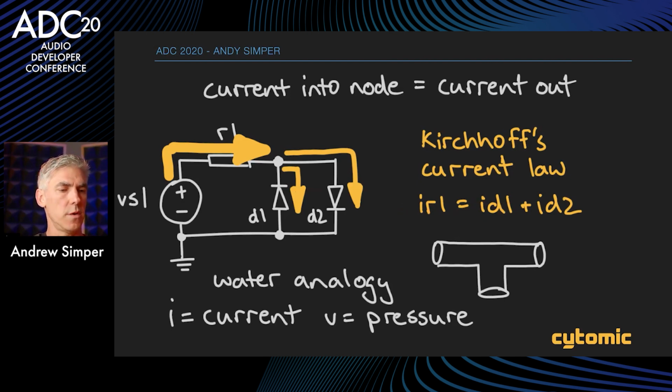The important thing to note here is that when you're dealing with circuits, you've got two numbers: the current and the voltage. This is the real world analogy. You still have a current, which is the flow of water, but the voltage is the pressure of the water. These are physical things that are natural with water. When you're into DSP, you're stuck with the V. You've got the signal and you're processing that, but you kind of forget about the current. You've separated those two. And in circuit modeling, you don't separate them. One leads to the other. This is the kind of trade-off that you get when you're modeling, in this case, not a physical system, but an electrical system. You don't get something for nothing. There are always little bends and trade-offs.